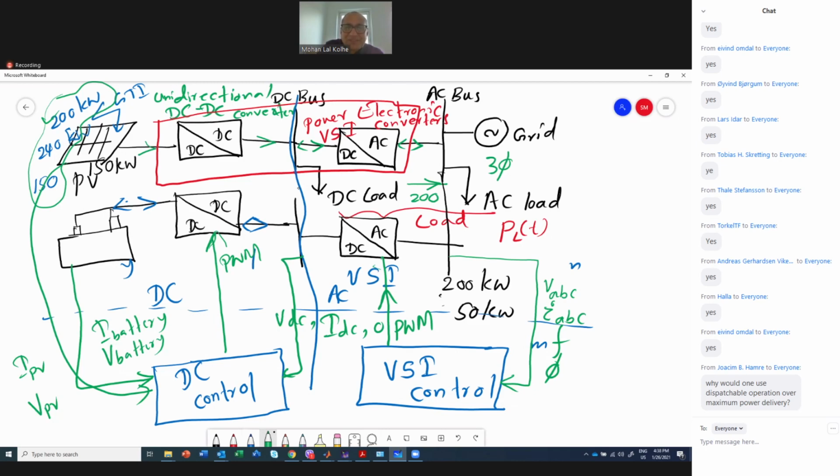Then to control this DC to DC converter, or basically the PWM signals, they will be based on different types of mechanisms, for example perturbation and observation, or maybe using some real-time parameters from the photovoltaic, such as solar insolation and operating characteristics. Those types of algorithms can be studied here when we want to implement them into this DC to DC converter control for maximum power point.